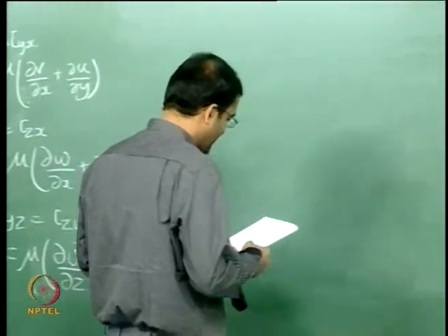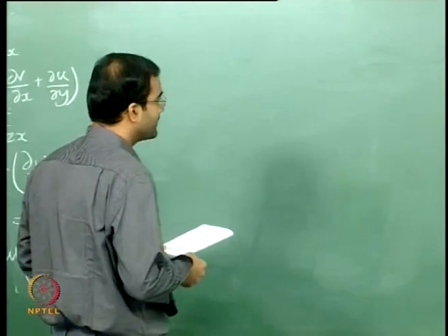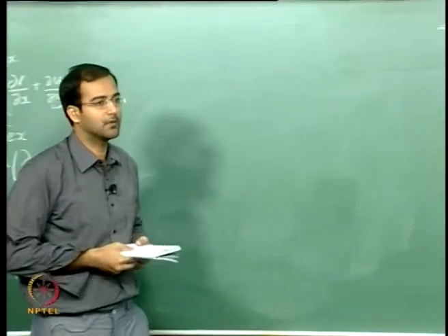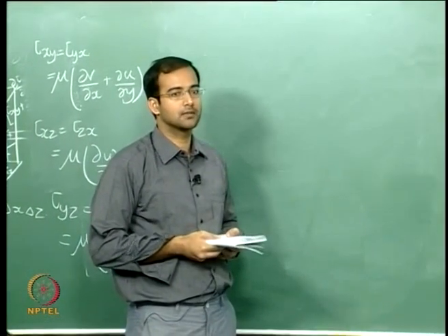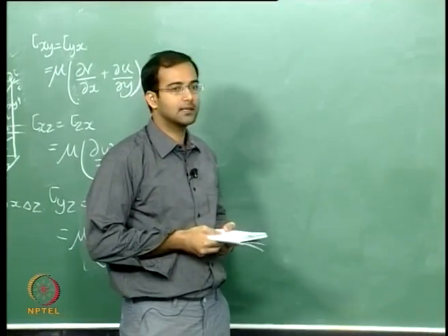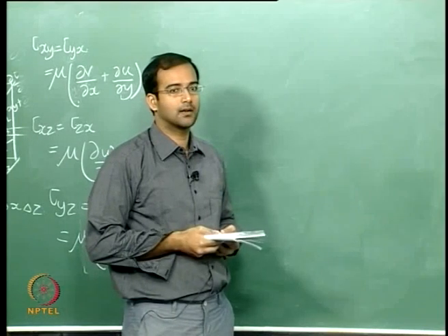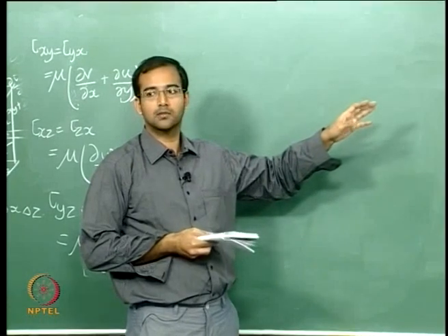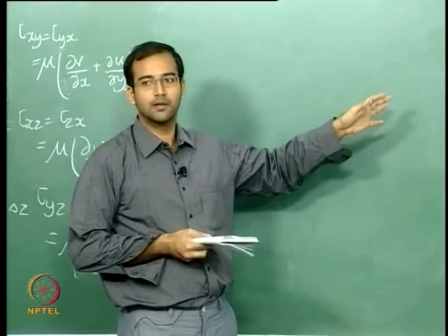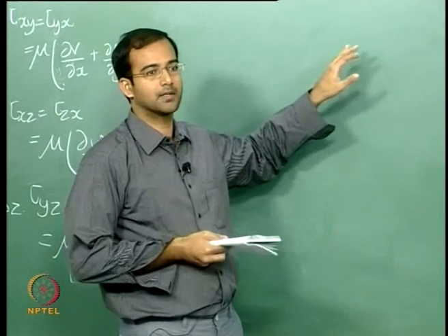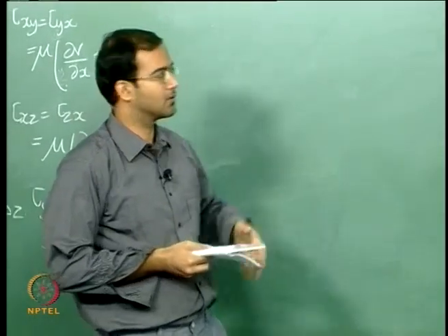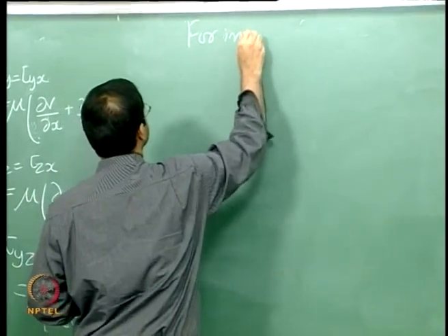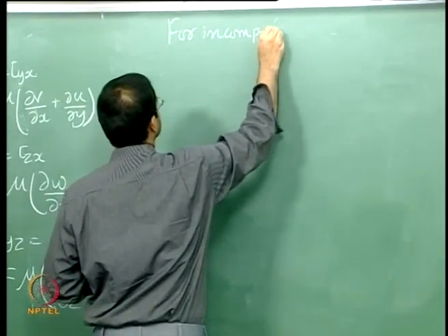Okay, so now I hope that you have completed the Z momentum. Now what we will do is, this is still not the simplified form of the Navier-Stokes that we would like to use. And as I said, we will be focusing primarily on incompressible flows. Now this is valid for both compressible and incompressible flows. We will introduce another approximation that we will be looking at only incompressible flows. So for that, you will see that magically many of the terms drop out,